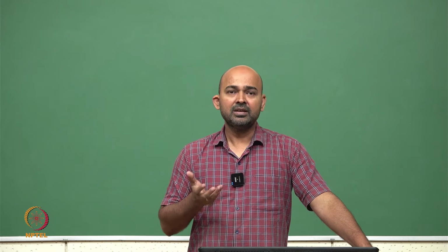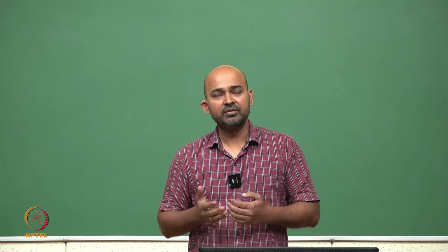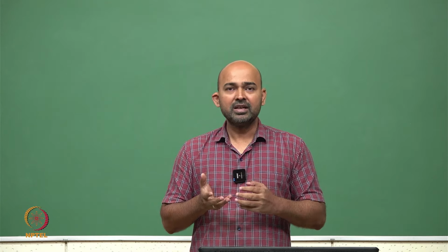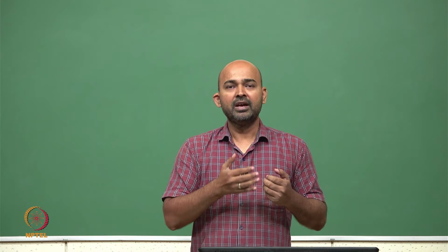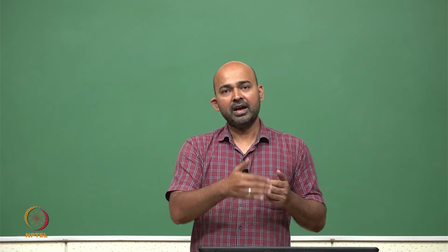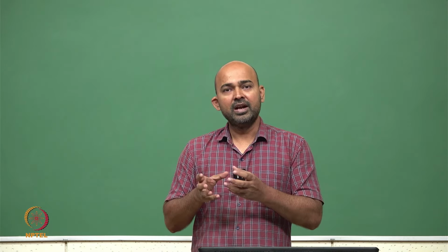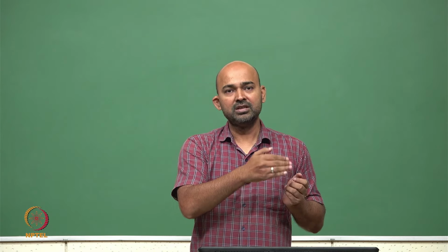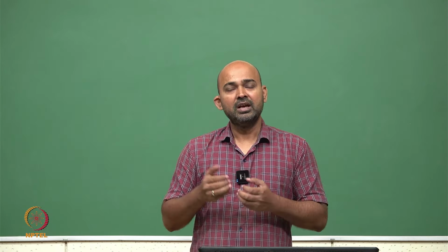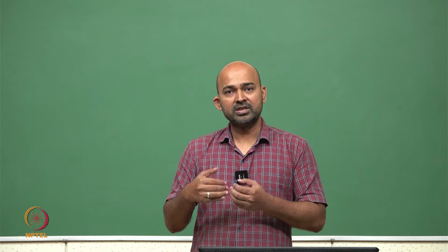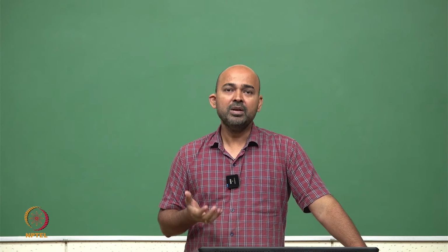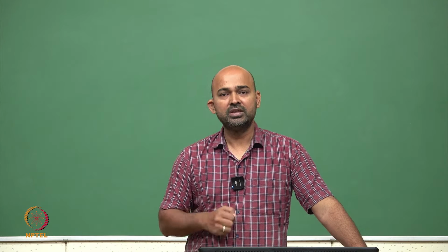So, we saw one circuit last time. Today we are going to see another circuit which is very important in digital design, which is called the full adder. This adder is a circuit which takes 2 inputs as input arguments, and one is the carry which comes from the previous stage. So, altogether there are 3 input variables A, B and the carry from the previous stage, and this full adder is adding these 2 inputs along with the carry, and generating the sum as the resultant, and there is a carry. If there is a carry formation, the carry output will be generated using this full adder. So, let us see how we can implement the full adder using the Verilog language using these free softwares.